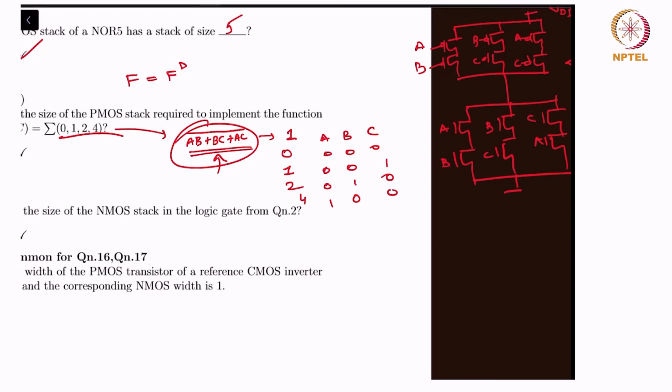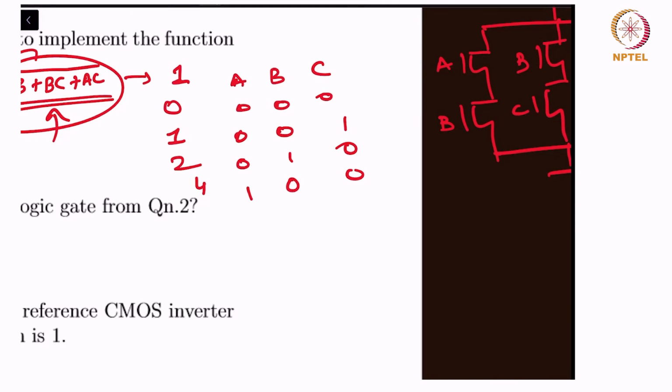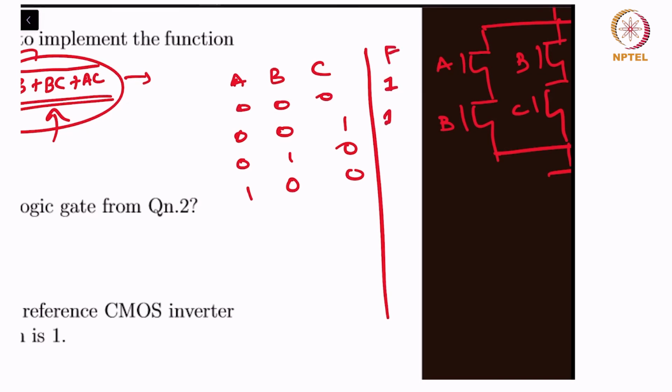if you were to complement all the min terms. So let's just do the truth table. For all these guys it's 1, and for the remaining guys it's 0. So let's say I complemented 0, 0, 0. So I get 1, 1, 1. The output is also complemented. 1 becomes 0. Similarly, I complement 0, 0, 1, right? So let's say this is now 1, 1, 0. The output is complemented, right?